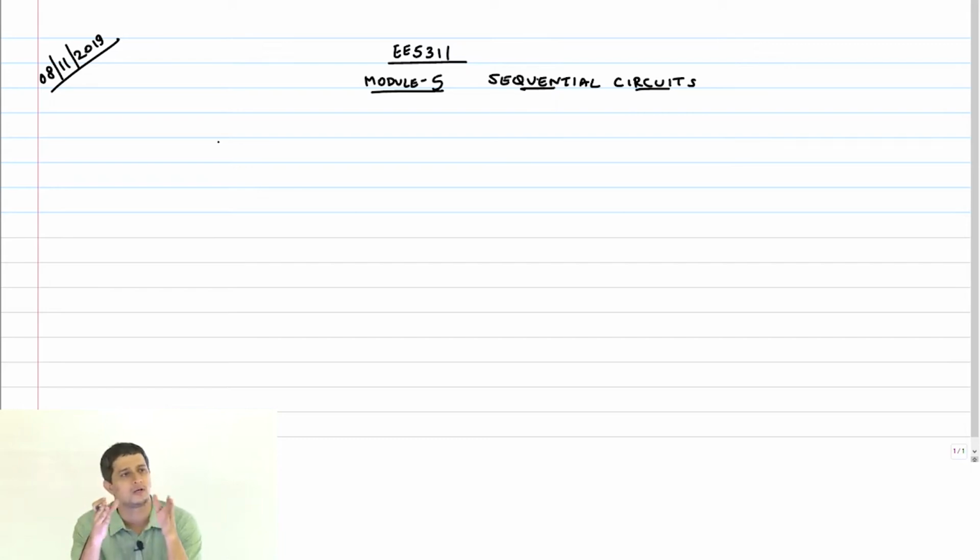Also, what the problem was, we probably didn't draw the timing to scale in terms of the contamination delay and the propagation delay, right? The contamination delay can be very small and the propagation delay can be quite large. Because of this, you will see a problem, but let's look at it now.